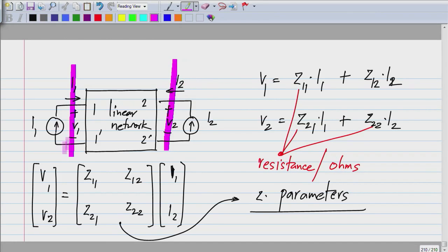Now in this case, I have applied I1 and I2 in the same direction. So just like previously, when I applied these voltage sources, I took upper one to be positive in both places. Now that's how these parameters are defined. If you apply an external current which is flowing downwards in both cases, it will simply become negative. That's all. So these are known as Z parameters. Now in the next lecture we can discuss this in some more detail.